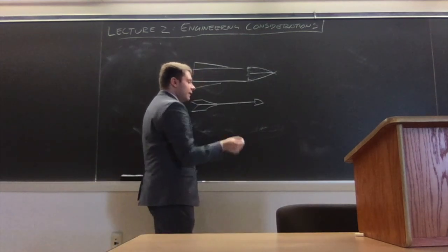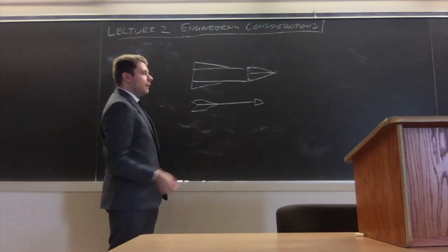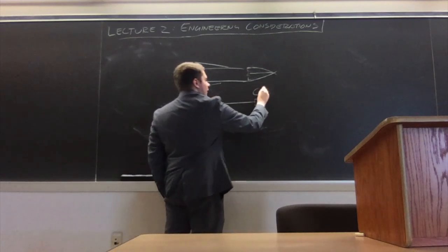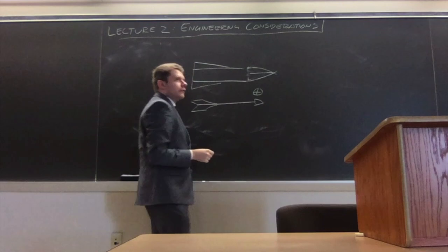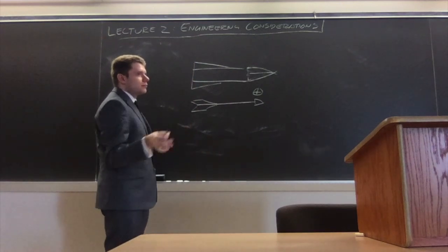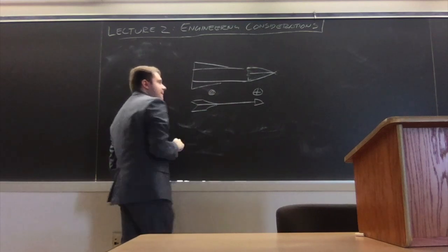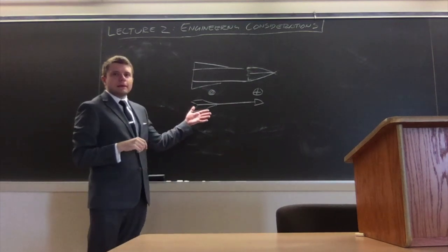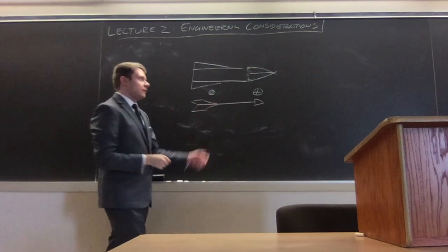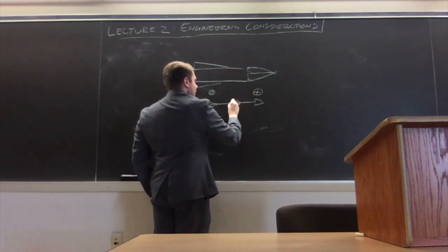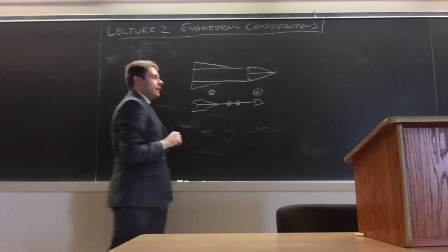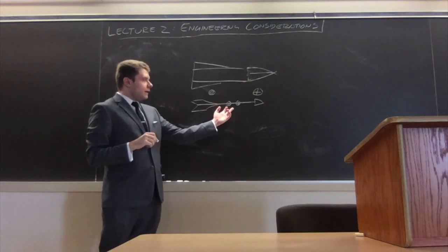And you look at an arrow, and you kind of understand the principles that go into building a rocket. There's a very heavy projectile in front. I'm going to use these symbols to indicate center of gravity and center of pressure. And there is a very draggy bit of back. Now, this is greatly exaggerated. Realistically speaking, they're probably like here and here in the actual arrow. But it means it's self-correcting.